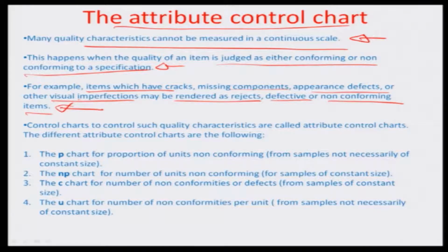So basically these are things for which there is no measurable basis of recording, and that chart is known as a P chart. The P chart is basically for the proportion of units which are non-conforming. When we talk about a fraction reject, that is what this term P means: out of 100 samples, if we have rejected 30 samples, our P value is 30% in that particular lot.